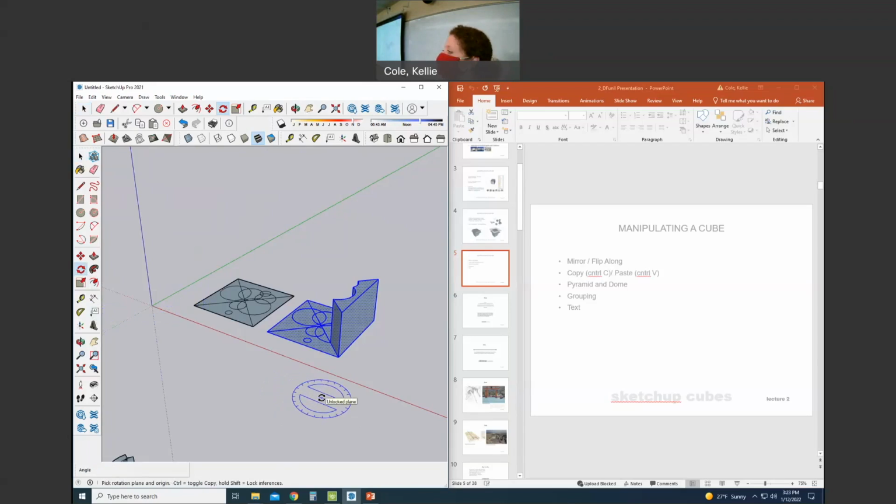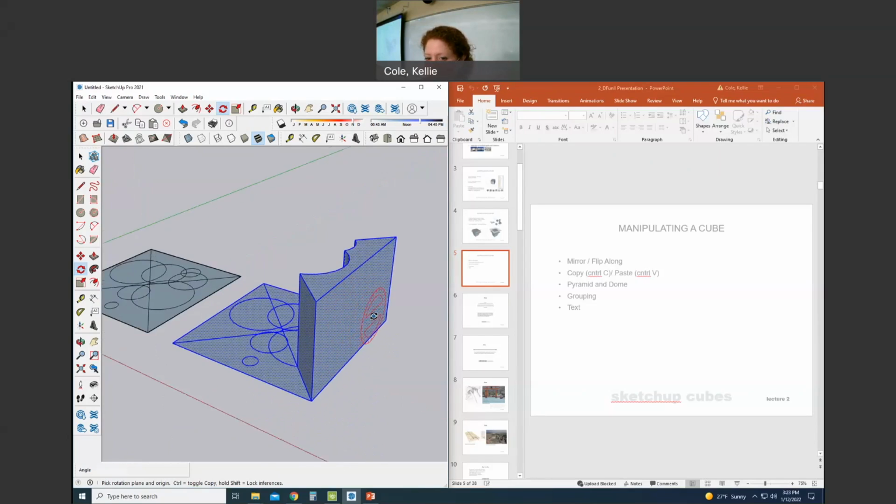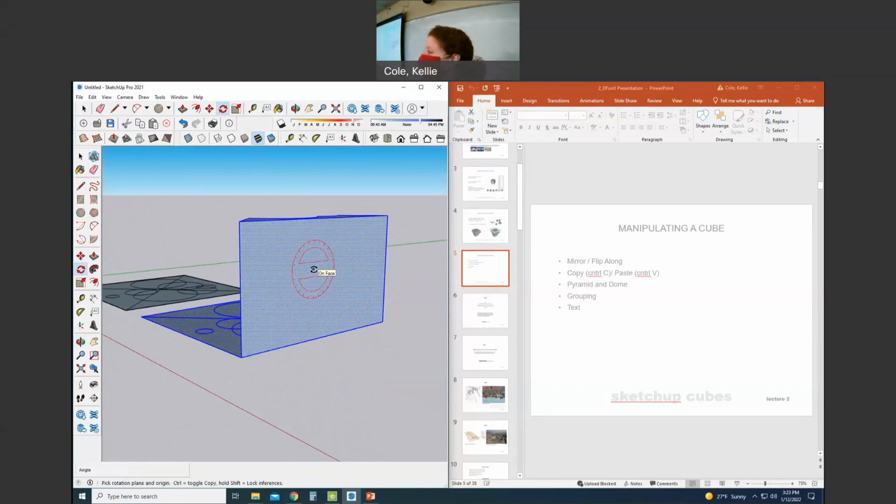All right, rotating is really particular in SketchUp, but once you get it, it's not that hard. What's going to come in is this blue protractor. If I hovered along that vertical face that I push-pulled, it turns red. Or if I hover it around the floor plan plane, it's blue.